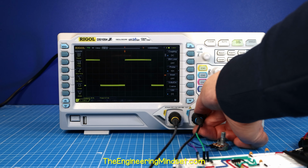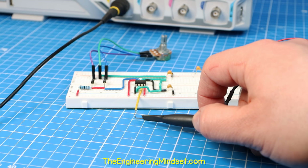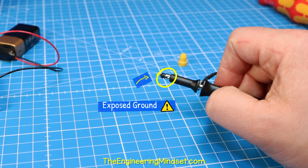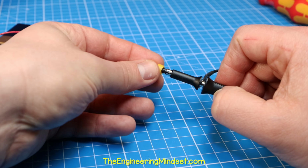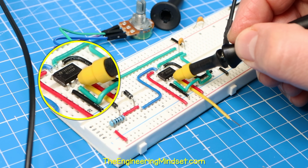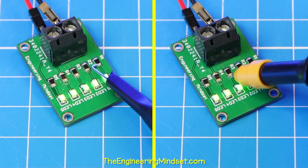Turn off channel 2 and disconnect the probe. Disconnect the channel 1 probe also. Then, with a small force, push the top off the probe to reveal a pointed tip. Place the insulating cap over the end. Now we can probe points of the circuit. This is very useful for SMD components.